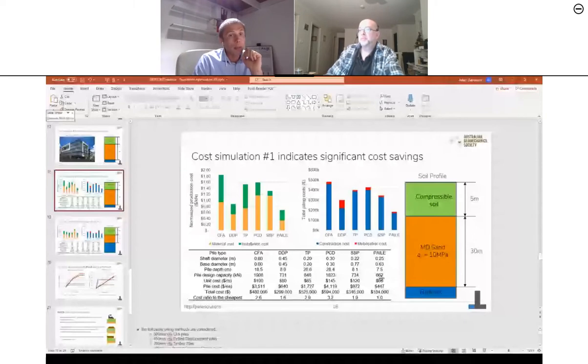But it can be more than that. It's pretty much driven by the structural capacity of the shaft and then how much resistance can be mobilized underneath. And if you look at helical piles, I know that they can be installed up to 600 mil shaft diameters. So quite significant loads could actually be taken by those piles.